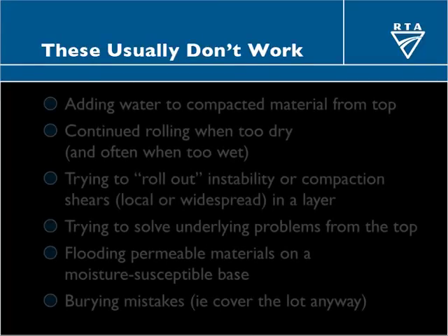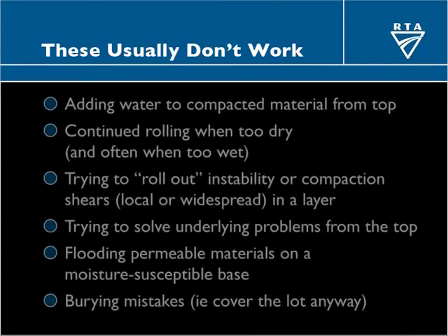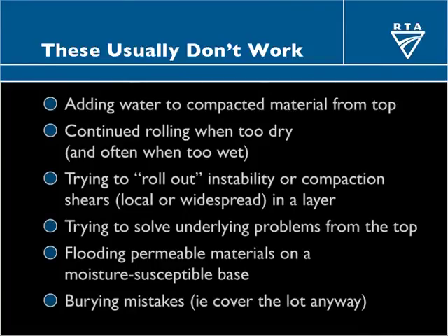Now, some things that usually don't work, again based on many years of bitter experience. If you've compacted the material, you're not going to have much joy just trying to get water into it by spraying on the top. It's hard to get it to soak in, and if it does, it's never evenly distributed. So it will either be hung up in the top of the material, or it will go straight to the bottom, the usual alternatives.